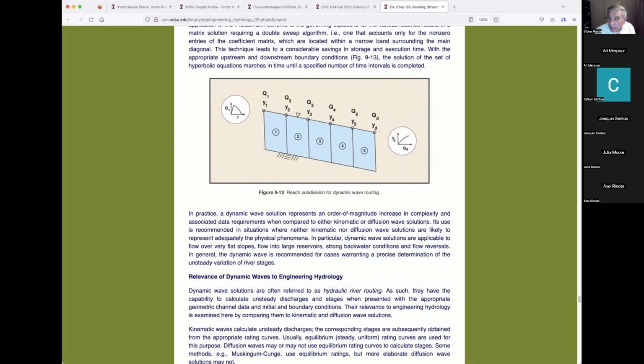But there are ifs and buts in regard to this. First of all, there's the issue of whether the wave does exist at all, but we'll settle that issue later on. The second issue is that you need a boundary condition upstream and another downstream. Otherwise, you can't solve it. Otherwise, you're going to have one less equation. In other words, we have in here, for instance, 5 reaches, and there are 2 equations, so there are 10 equations. I'm sorry, that's the reaches, but the cross sections are 1, 2, 3, 4, 5, 6. There are 12 unknowns. So if we put in one boundary condition, we're going to be short. We have to put in 2 boundary conditions in order to be okay.